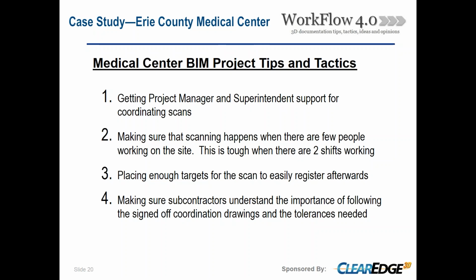So the manager, project manager and superintendent: getting their support, their buy-in, their feedback, and making sure they're involved. Making sure scanning happens when ideally there's nobody else in there, or as few people as possible, so you're getting the data that works for what you need it for. I don't know about anybody else, but I did not want to scan at 1 in the morning. So we tried to work around that as best as possible, sometimes catching lunch breaks or afternoon breaks. Placing enough targets for the scan to easily register.